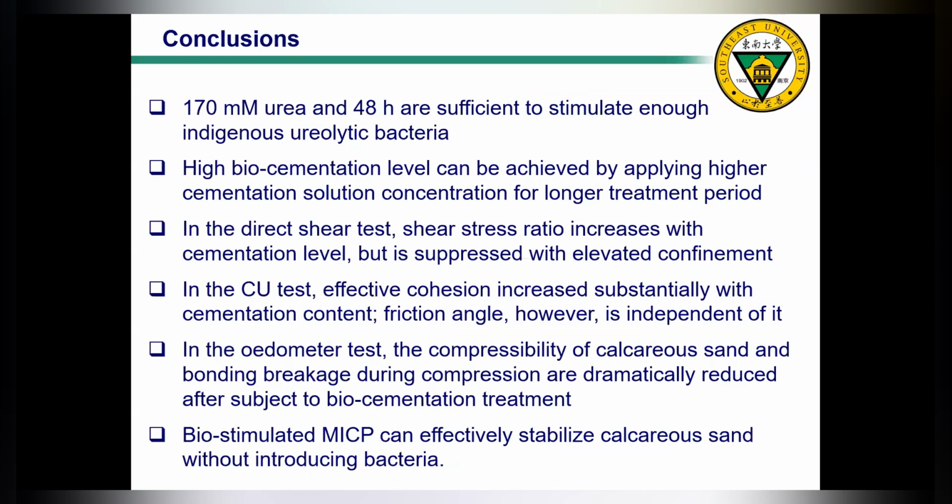Okay, so these are the mechanical performances we obtained from the series of tests, and here are the main conclusions. Firstly, we find that 170 mM urea and 48 hours of stimulation time are sufficient to stimulate enough indigenous ureolytic bacteria. Secondly, high bio-cementation level can be achieved by applying higher cementation solution concentration and a longer treatment period.